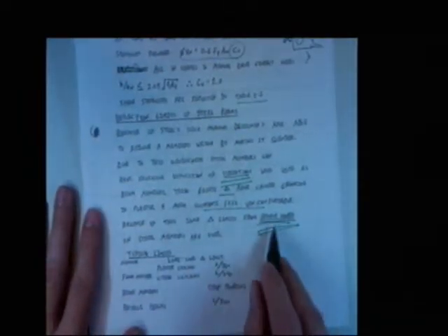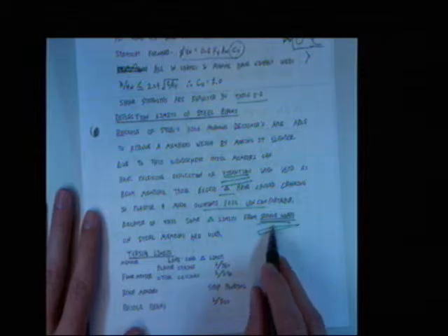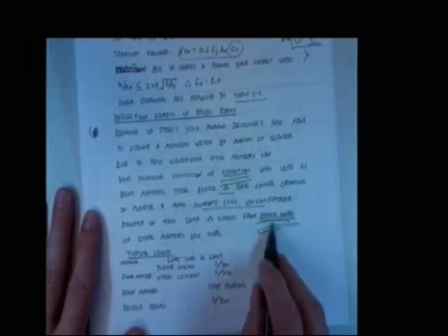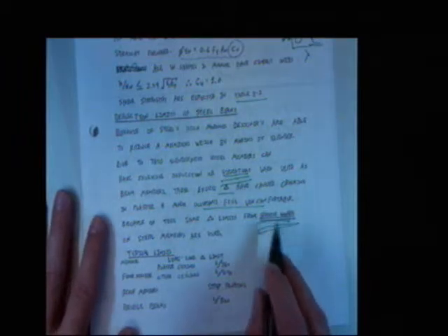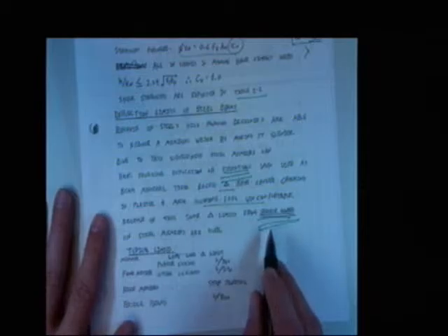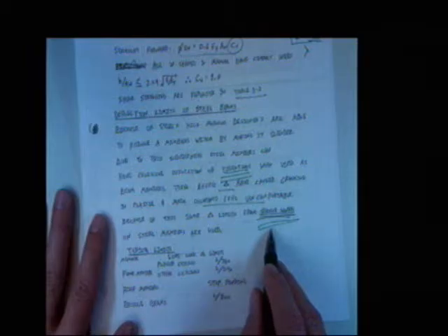So we care and we check for deflections and movements on service loads. That means live loads. Okay? Live load deflection limits. That means cars, people, things like that. It's not dead load deflection limits. It's really important. You also don't use a load factor when you calculate deflection limits. No load factors. Okay? No load factors involved.